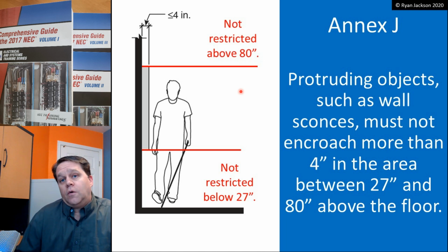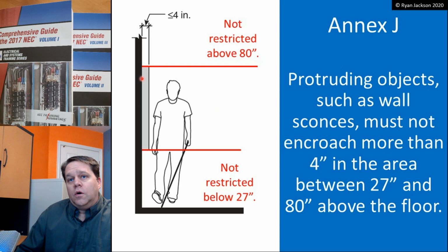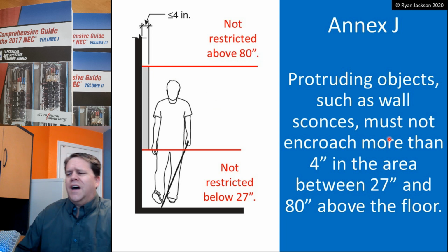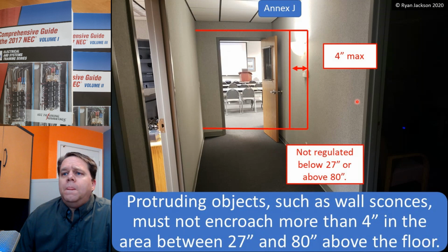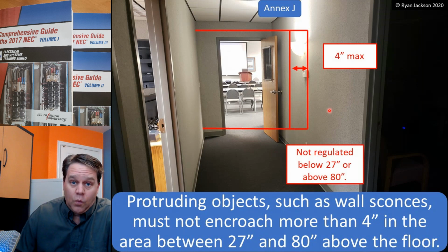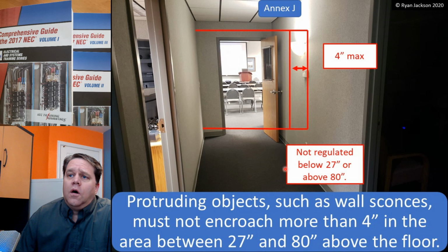If it sticks out less than 4 inches, beautiful. You can put it wherever you want. If it sticks out more than 4 inches, then you need to make sure that no part of it hangs lower than 80 inches. So be quite careful on that. I wrote this up as an inspector all the time. Very, very common violation. So here in this photograph, we have a violation. When this building was built, it was not a violation. I do want to emphasize that. This is actually one of the clients that I teach for. But you've got these wall sconces that stick out more than 4 inches. They are above 27. They're lower than 6'8", 80 inches. So that's a violation. They're not allowed to stick out more than 4 inches.